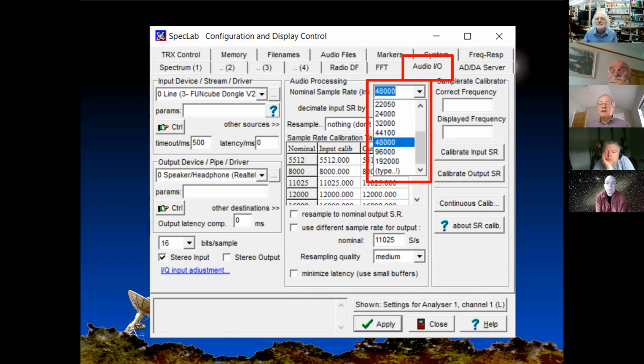You don't want a different sampling rate in your sound card to the rest of the system. So if you add a new USB card, go into Control Panel in Windows, look at the new device, and make sure the setting is at 48,000 or 96,000 if that device supports that operation. Okay, onward.